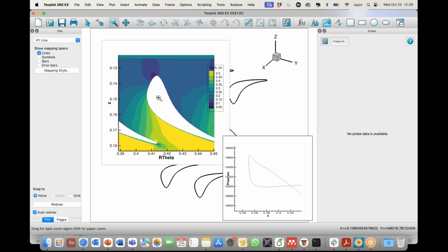Or another thing, which is probably more advanced, is playing a bit with the stator design, maybe changing the pitch. The effect usually is that the induced velocity component at the inlet, due to the circulation of the vane, changes, and because of that you have a different incoming velocity. And playing with the spacing, you can play around a little bit with where this stagnation point lays.